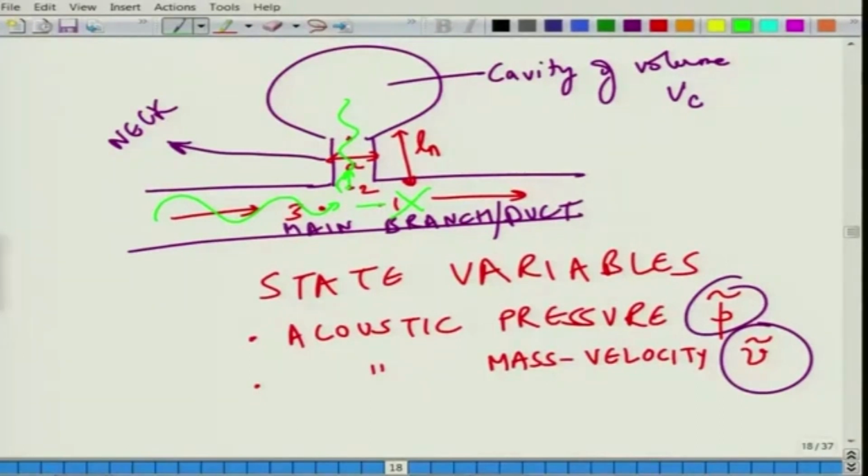So it is in a way using the impedance mismatch or impedance matching principle to divert or deflect acoustic waves in a certain direction and not allow the waves to propagate downstream where you might have a listener. So this is your ear where you listen, you do not want the noise to come here. So how do we go about it? The idea is basically, let us write down the equivalent or the effective impedance seen at the point 2.